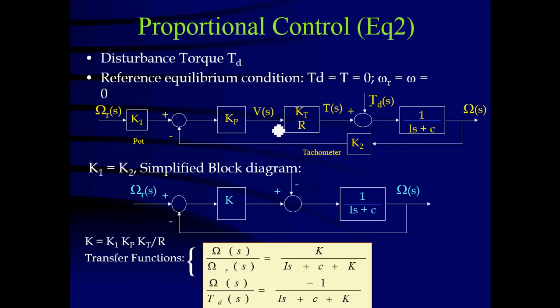These are the transfer functions that you can have, because now you realize that this one is an input to the system. This is your input. But isn't it true that this disturbance here is also an input to the system? I'm going to call it input disturbance.